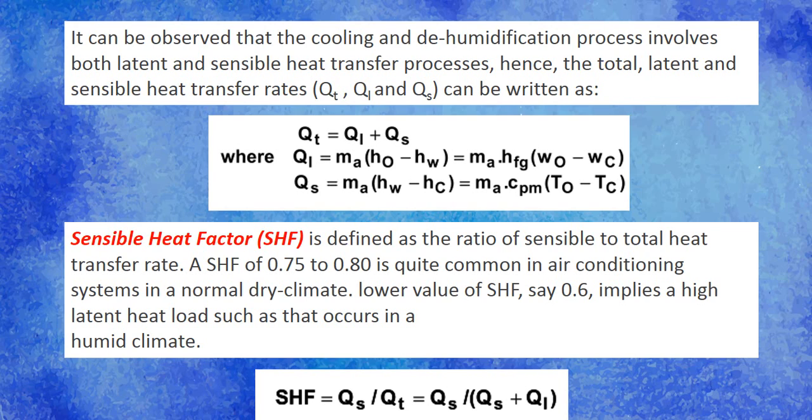Now, this definition, the ratio of sensible to total heat transfer rate, translated in the form of a formula, would be your formula: the sensible heat transferred over the total heat transferred, or the load of your cooling coil. Okay, the ratio, so it's dimensionless.